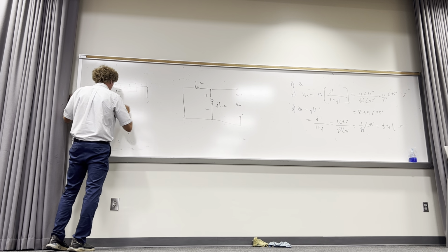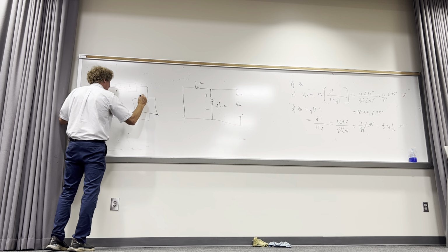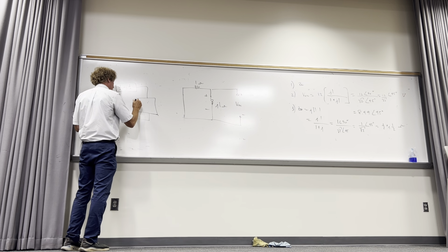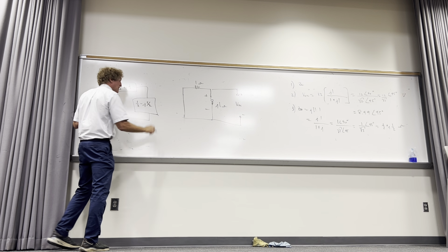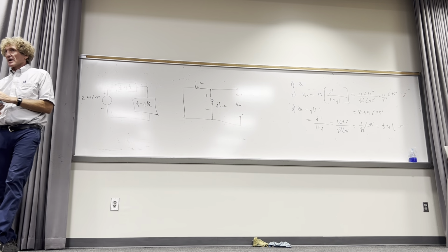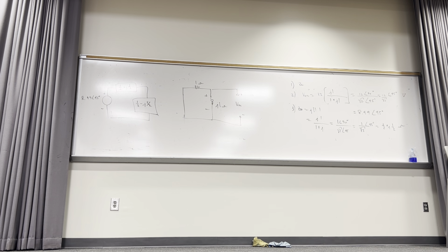And now, what is the load impedance going to have to be because of that? 1/2 minus J1/2. Exactly. Follow me? That will maximize power. What is the power that will be absorbed by the load, class?